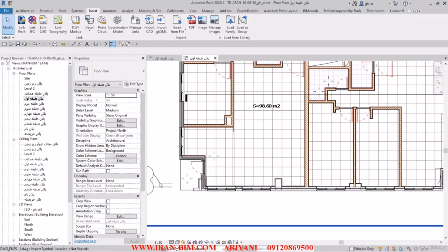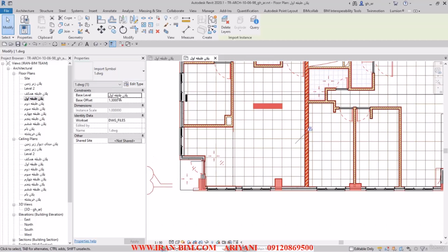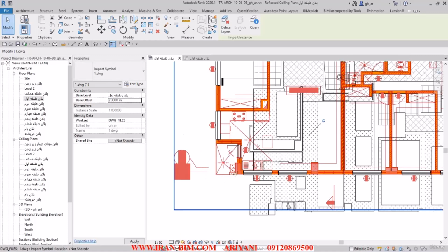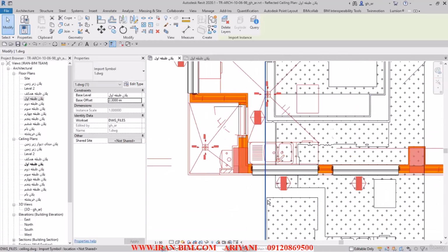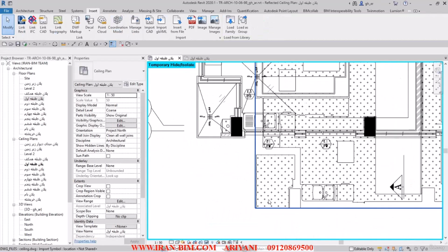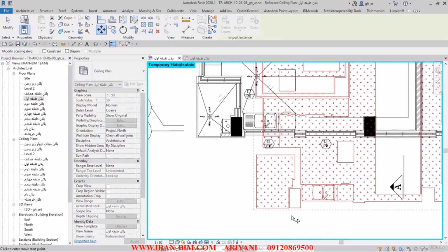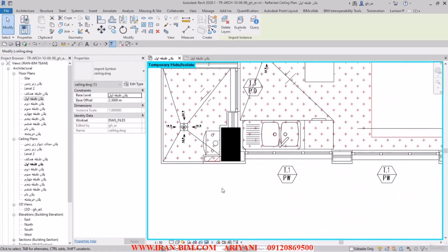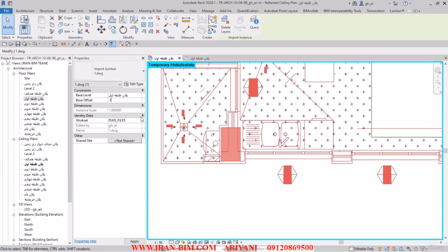Then let's go back to the first floor plan. And then here I'll drag the CAD file itself for 2 meters upwards. Let's put it on 2.3. And then I'll isolate these two over here. Then select this one. Select the move tool. And then I'll link up the corner from here to this one. And then I'll put the offset to where it was originally.